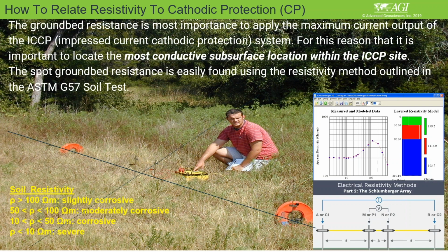to connect your current or voltage injection to the ground easily. So that means the ground needs to be in clay zone areas. These clay zone areas can be found through vertical electric sounding, if you're doing just four electrode measurement manually. Typically it's the Wenner, but you can also perform the Schlumberger over here. One thing you do is sometimes you measure along this line, where you design your measurement. And sometimes it also requires the cross line of this measurement, just to make sure of any variation in the